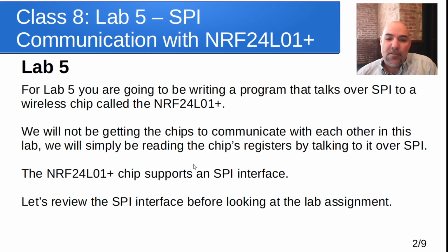Now, for this lab, we're going to write a program that talks over SPI to that wireless chip. You're not going to be getting the chips to communicate with each other for this lab. In other words, you're not going to be using any of the wireless capability. We just want to make sure, can I read registers from that chip? And then ultimately, can I write registers to that chip? We're not going to do any writing to it today, but it's the same process that you'd use to write over SPI as read over SPI.